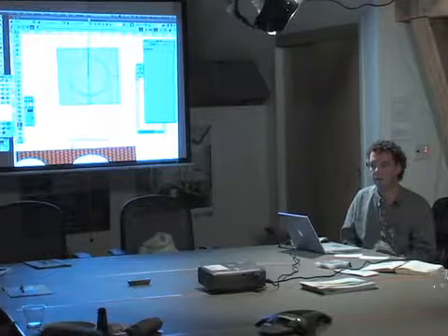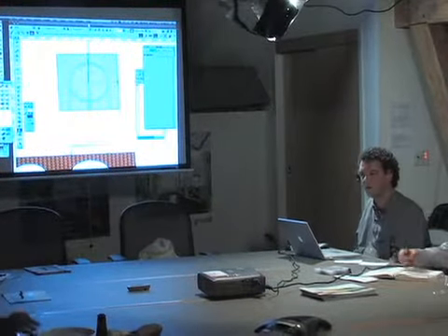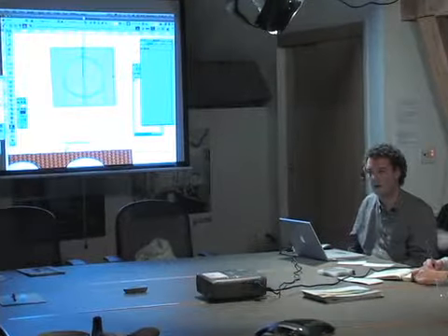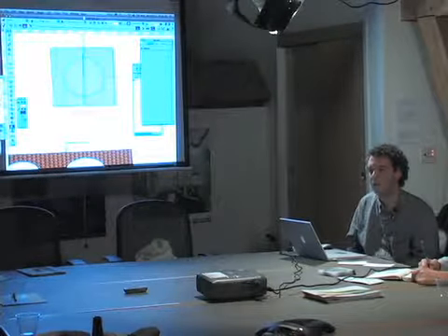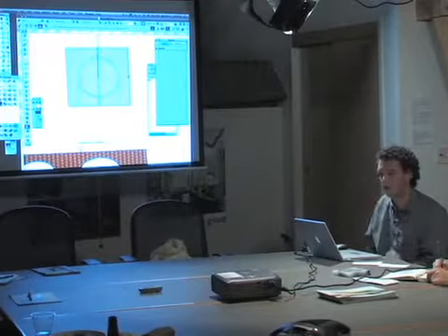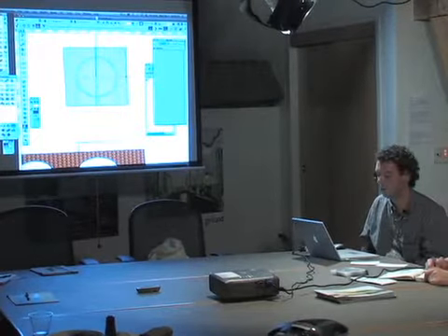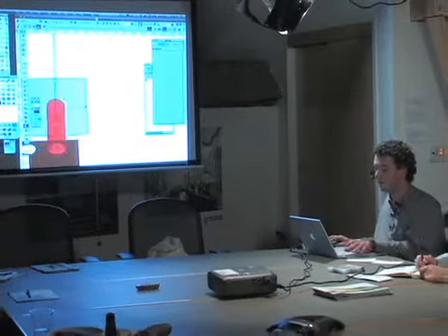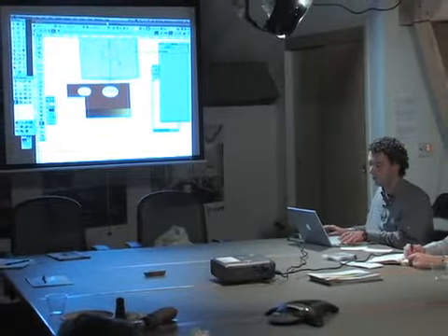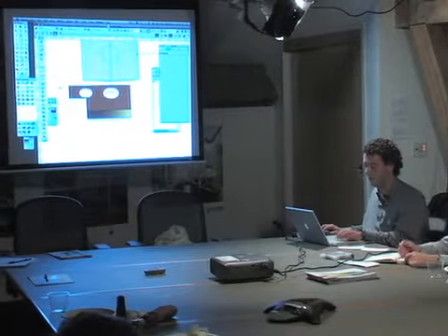So you don't have to go into RenderWorks and do all the rendering of a model to get some textures or imply a brick pattern on your building. You can use some tiles. You can still use the old hatches, but you're going to apply them directly to your model and have it stay with your model.